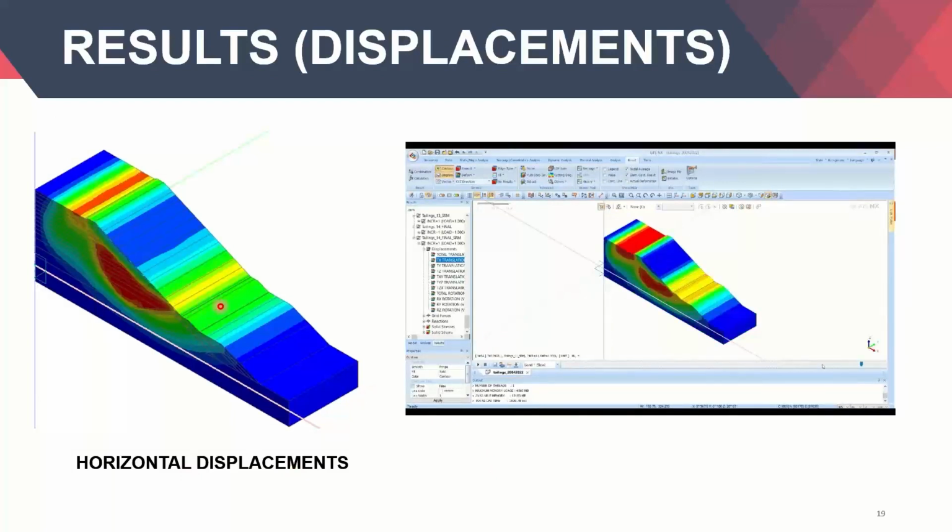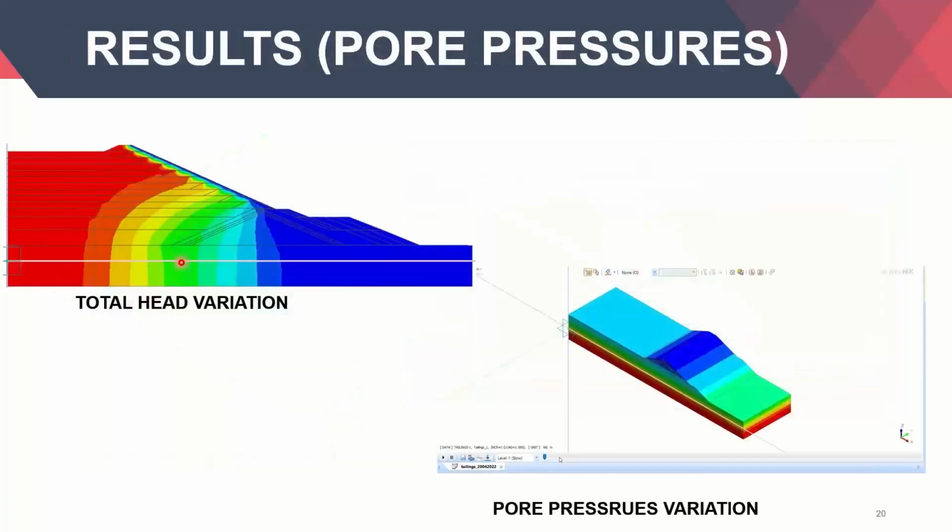That means it is entirely trying to push the slope outside, which essentially reduces the effective stresses on the outskirts or on the edges of the model. And normally this is also the same case in dams. Due to lack of confinement, we experience small local failures. So our job is to ensure that these small local failures remain small, they don't become big, which is why we do a numerical model.